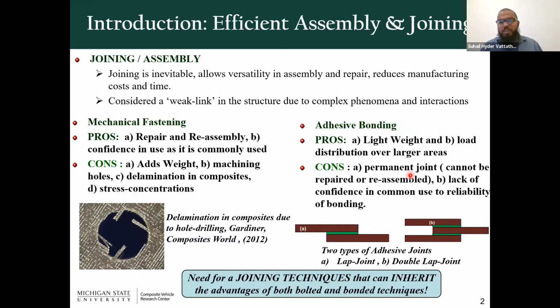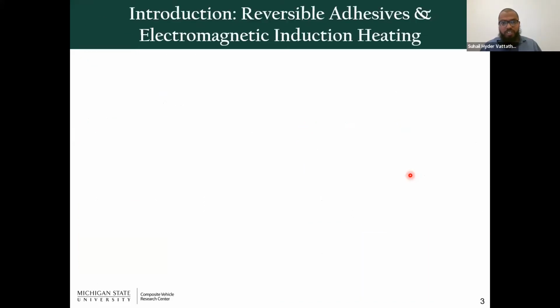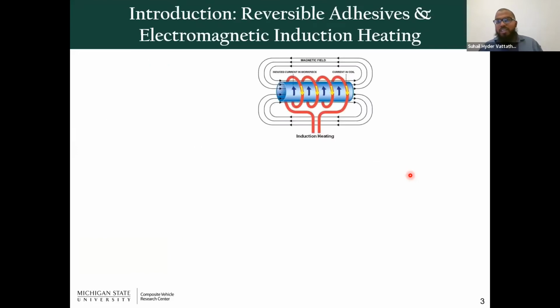So we thought of developing a separate adhesive called a reversible adhesive and using a different heating technique other than the conventional oven, and that is the electromagnetic induction heating technique. According to this technique, any conductive particles or any conductive object, if placed within a changing magnetic field, will generate heat by means of Joule's effect or by hysteresis.